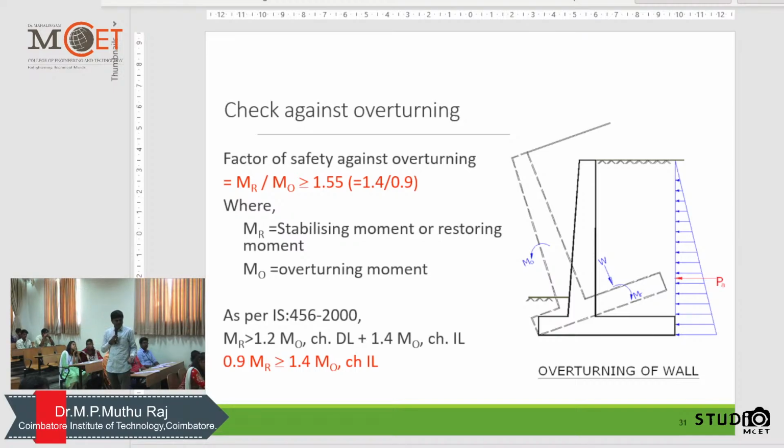The maximum pressure will be offered from the toe end. So here, the condition is that the pressure at this end should not be more than, say, the bearing capacity of the soil. Even though you are resisting the tension, at the same time, you have to verify one more thing also. At this point, there should not be any more pressure than your bearing ability of the soil.